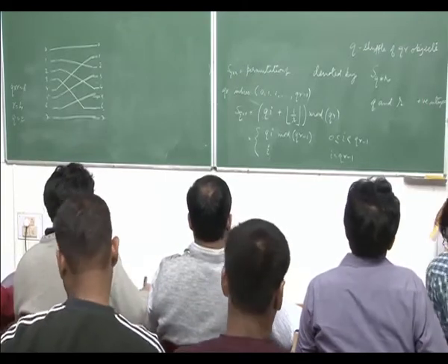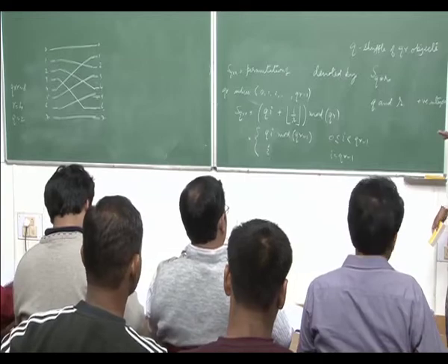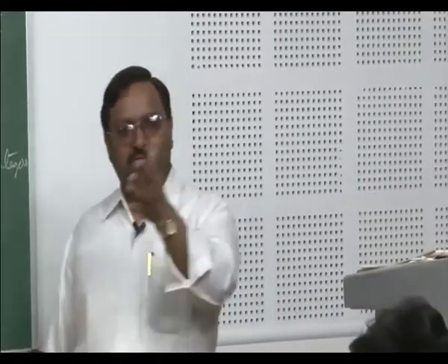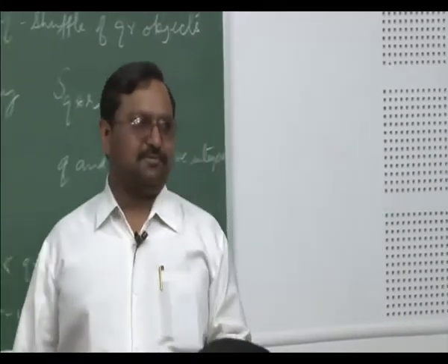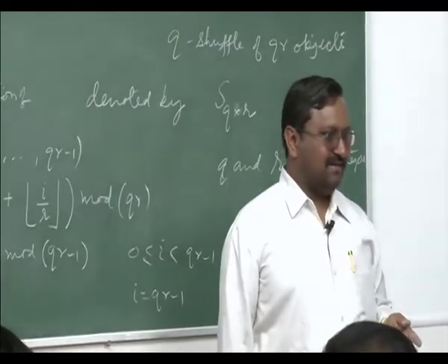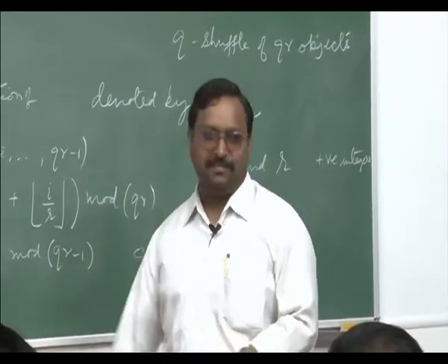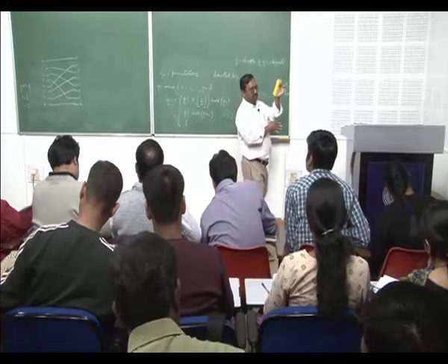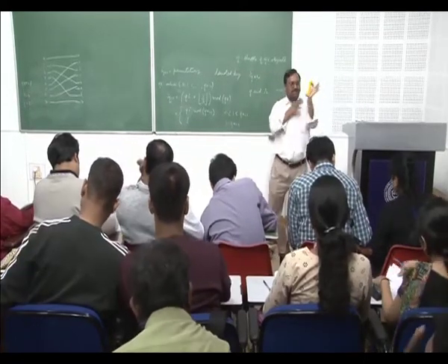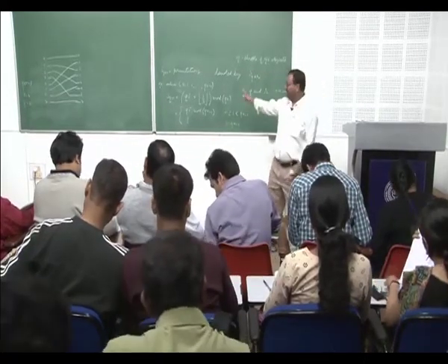So, shuffle now we have understood. I will take exactly this thing and we will start a formal proof that a shuffle net actually is a delta network, a generalized shuffle net, which will follow this interconnection pattern from the output of the ith stage to the i plus first stage. Mapping is done as per this.